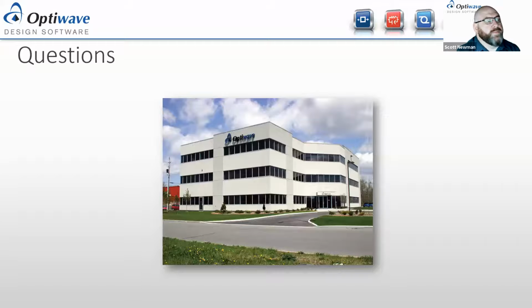This was one that I see here. The R over A value, I mentioned the complete band gap. So R over A should be 0.48 for complete band gap. I didn't use that. The reason I didn't use that is it brings the holes really close together and you have to run very high resolutions. And if I was going to run simulations during the webinar, that wouldn't have been feasible. So I didn't want to do that.